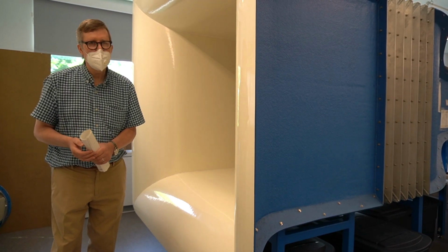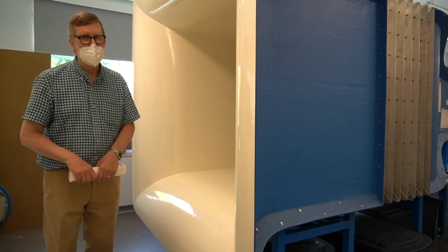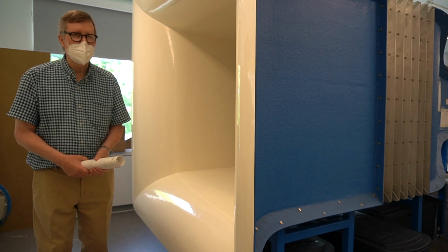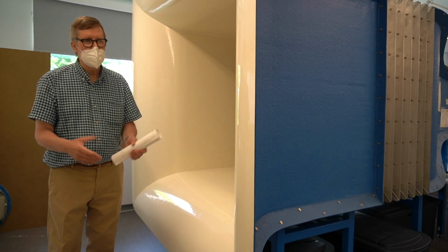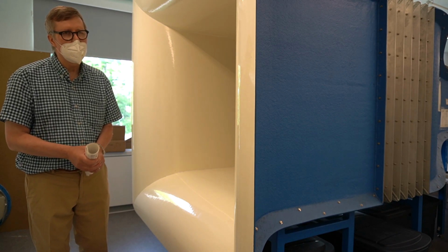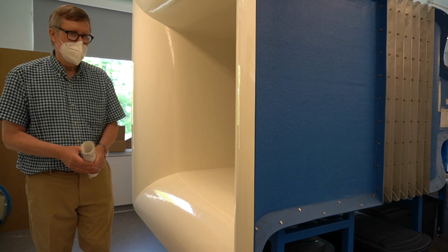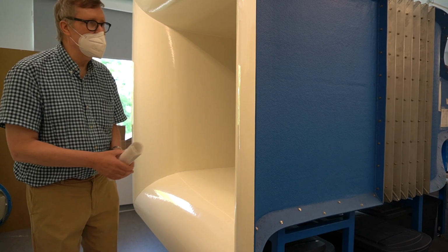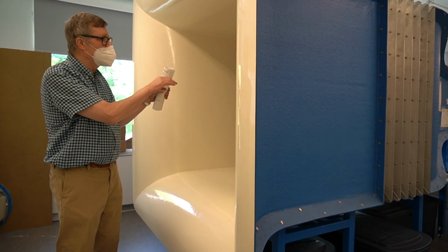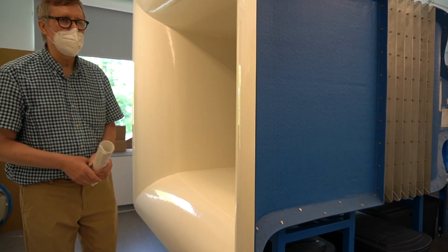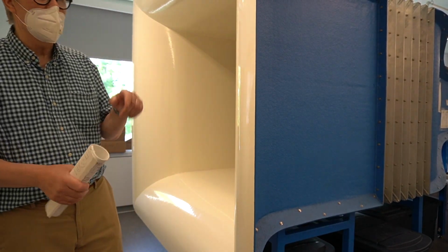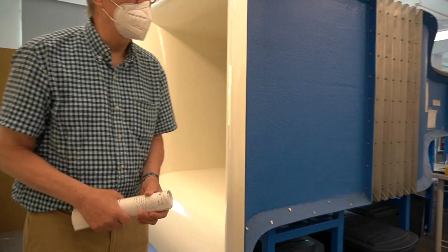Well, it's reducing the turbulent structures in the flow, making it nice and smooth flow, and it gets down to root mean square turbulent structures of 0.01%. So that's really amazing. The other thing it does is it increases the uniformity. That is, it makes the flow speed at all different points in a cross section the same. So that's called uniform flow. Don't forget, that's not the same as steady flow or unsteady flow.